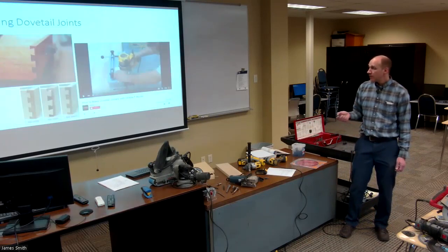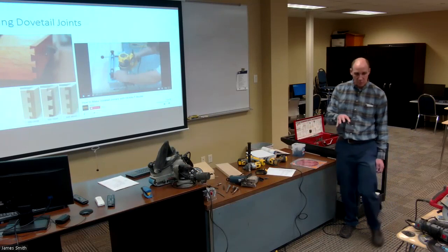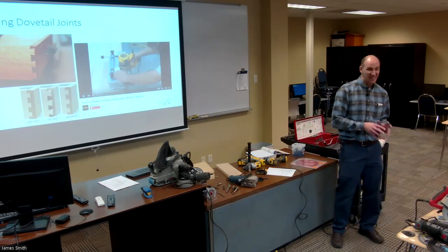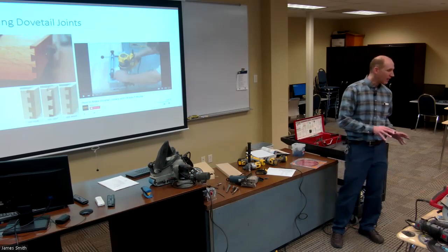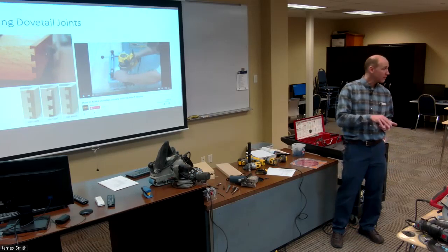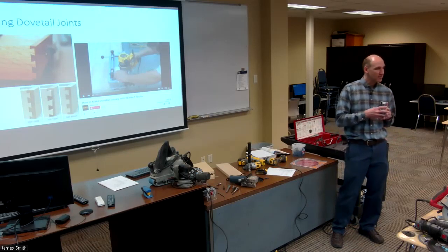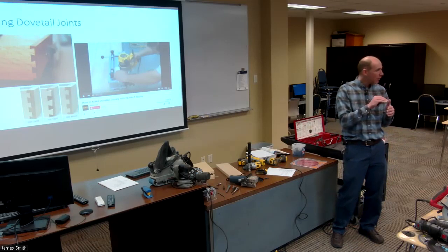There it is again. I have one of these Porter Cable routers that has a dovetail bit installed in it. That's all I ever use it for, and so I keep it in my cabinet hidden away so that dovetail bit doesn't accidentally get moved. Okay, because getting the dovetail joint to fit just right is a matter of how much your dovetail bit sticks below the base.